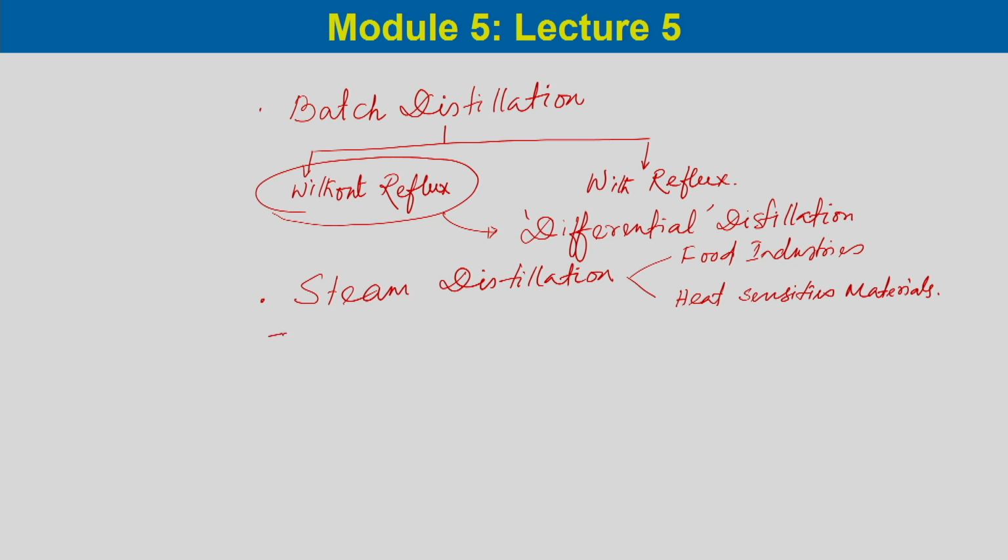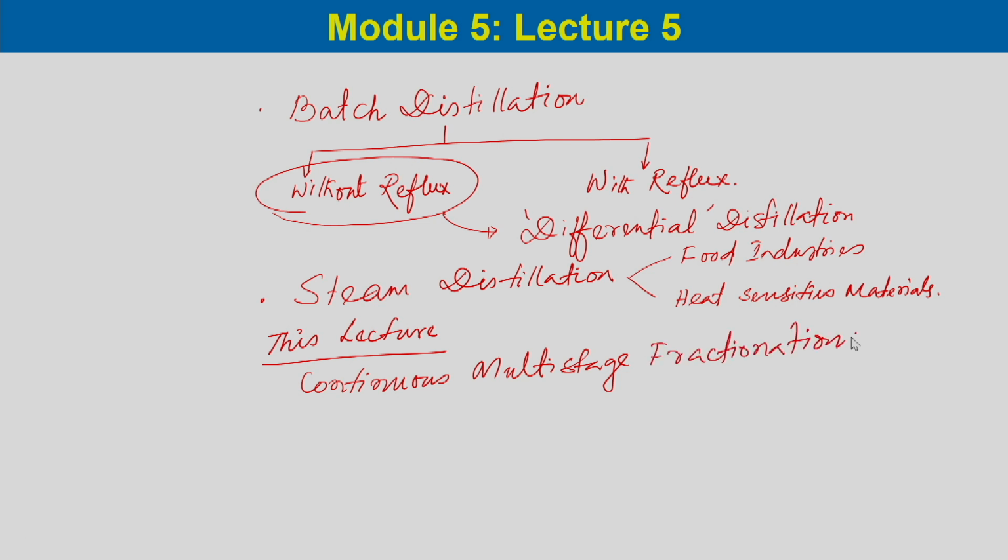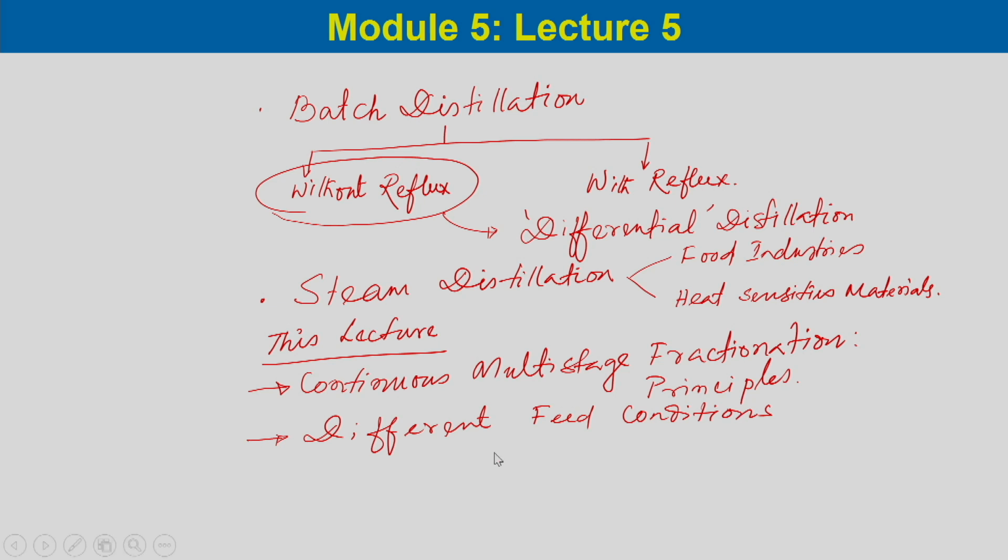In this lecture, we will mainly consider the continuous multi-stage fractionation, its principle. And the second thing we will consider is the different feed conditions, and based on the feed conditions, how these feed conditions change the flows of the vapor and liquid in the column internals.